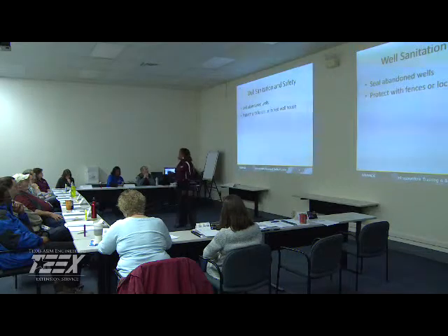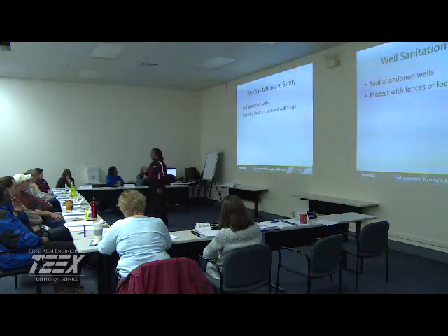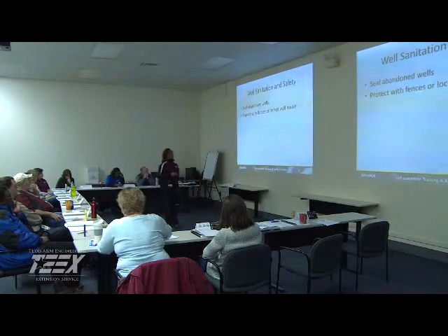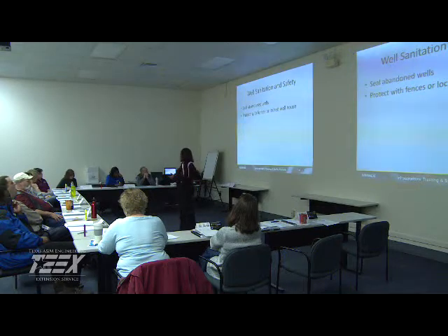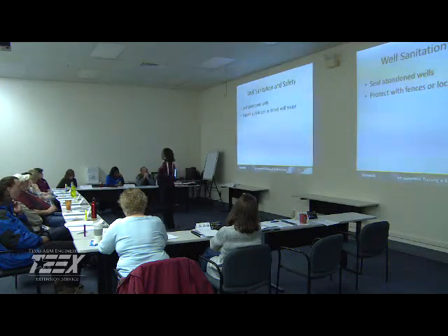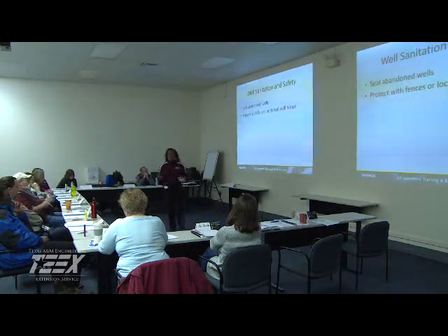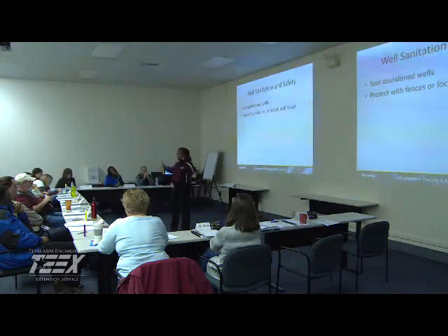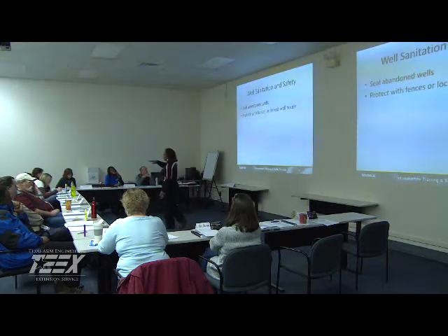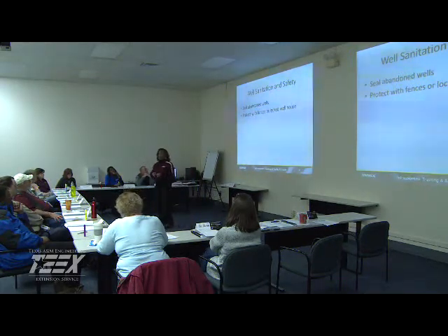Now, as far as sanitation for wells, if you have a well that is no longer in use, you want to make sure that you are sealing all abandoned wells. And again, you can look in the rules and regs to see what the requirements are for that. Your wells should be protected with fences or locked houses. And when you look at what the rule says as far as your fences, it gives very specific specifications. They must be a minimum of how high? You don't have any here. Okay. 6 feet, 3 strings of barbed wire, or 8 feet tall.